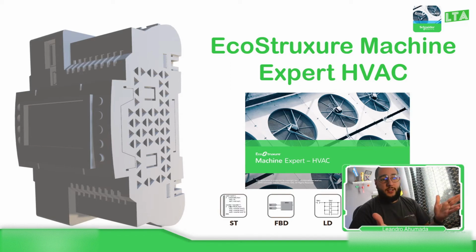One good thing is that it's free, and it has 5 different languages: structured text, function block diagram, ladder, instruction list, and sequential function chart, similar to GraphSet. So we have all those different languages available inside this software, which is good. For example, if you compare with the M171, the M171 has only the GraphSet, instruction list, and ladder. Here you have a bunch of languages.